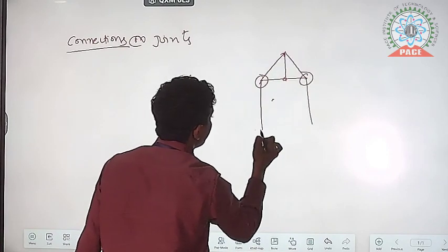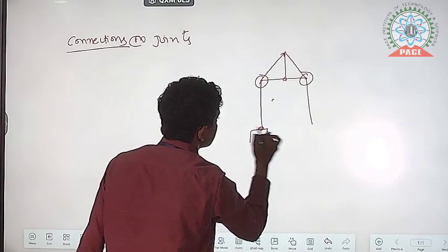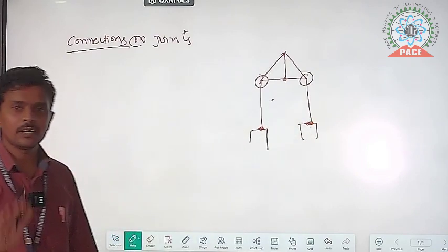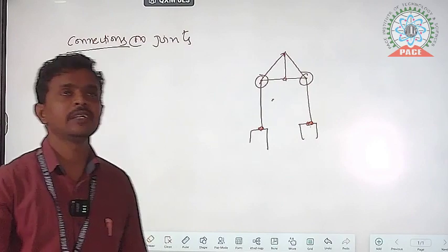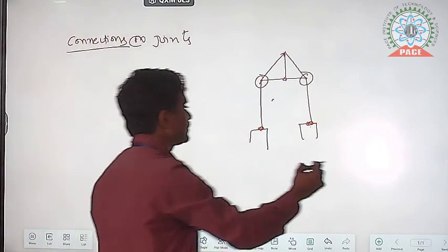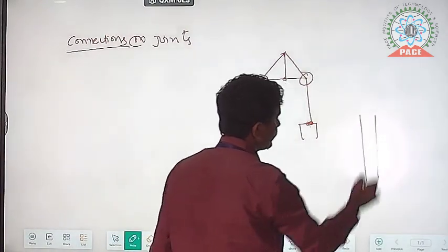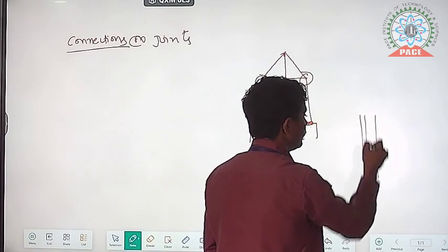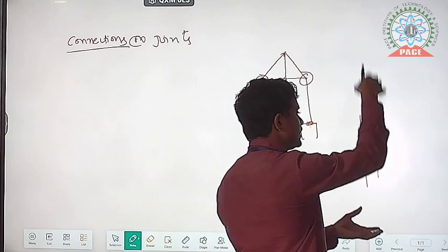Actually, in concrete structures, for example if any beam is there, simply we make the formwork, then keep the reinforcement, place the concrete and do the compaction, and later curing everything will be there.